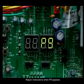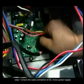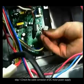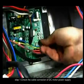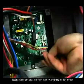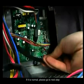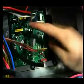Repair instructions when P9 appears. Step 1. Check the cable connector of DC motor power supply, feedback line or signal wire from the main PC board to the fan module. If it is badly connected or loosened, reconnect it. If it is normal, please go to the next step.